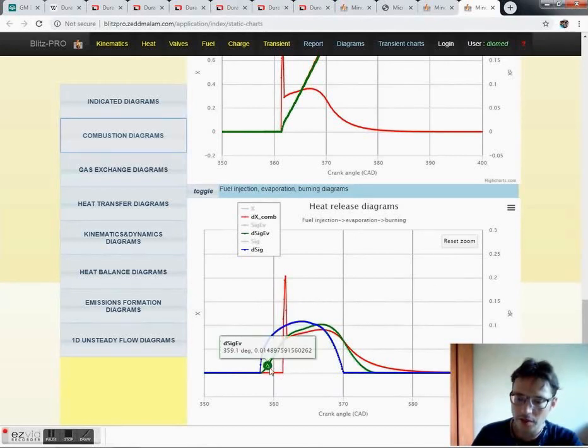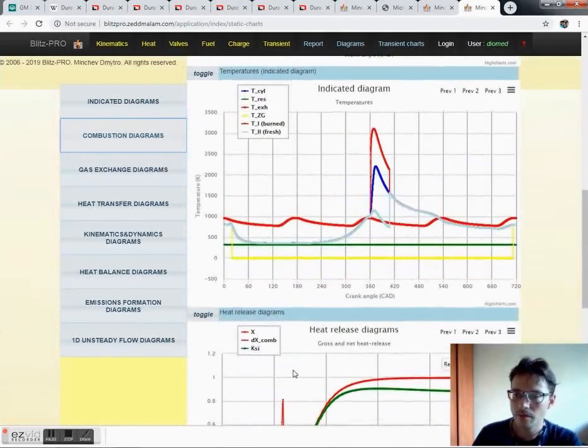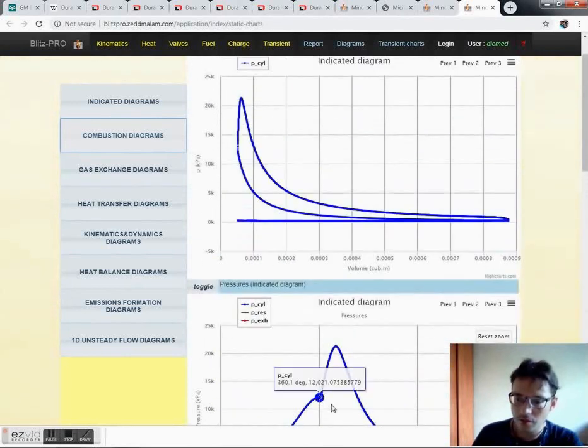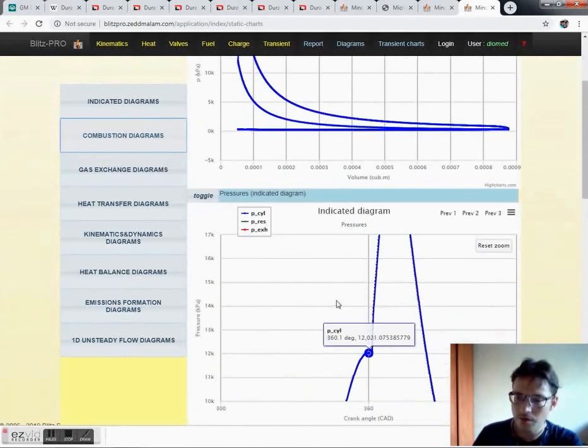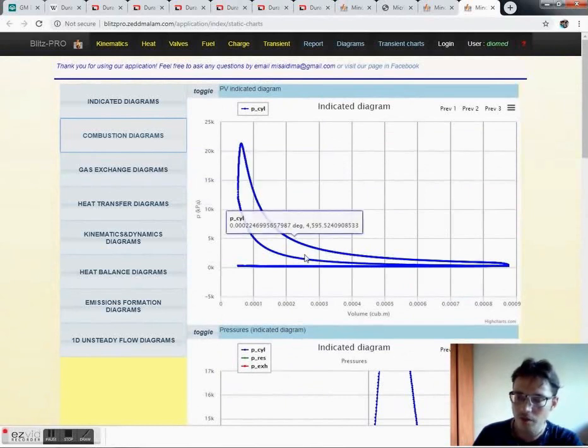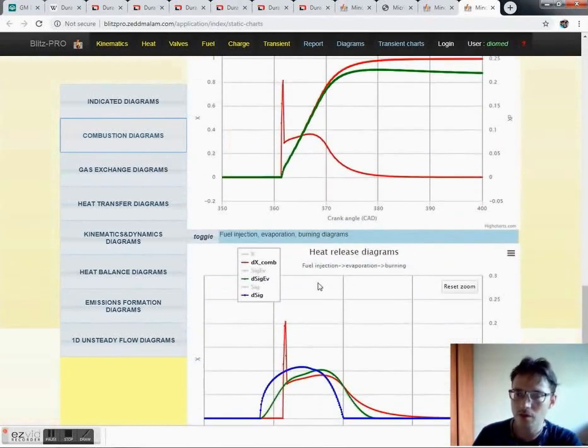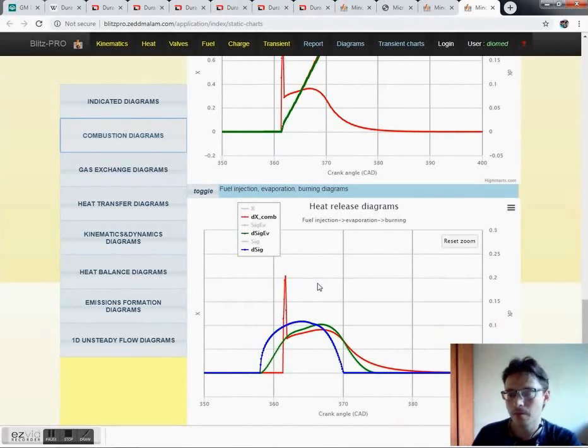And so when ignition occurs, all this fuel burns very rapidly, and this produces this rise in pressure in the cylinder at the beginning of combustion, this knocking, and also this high level of the pressure in the cylinder. So how to deal with it? Well, why is it so? It is so because the fuel is injected very fast. You can see only 12 degrees by crank angle.